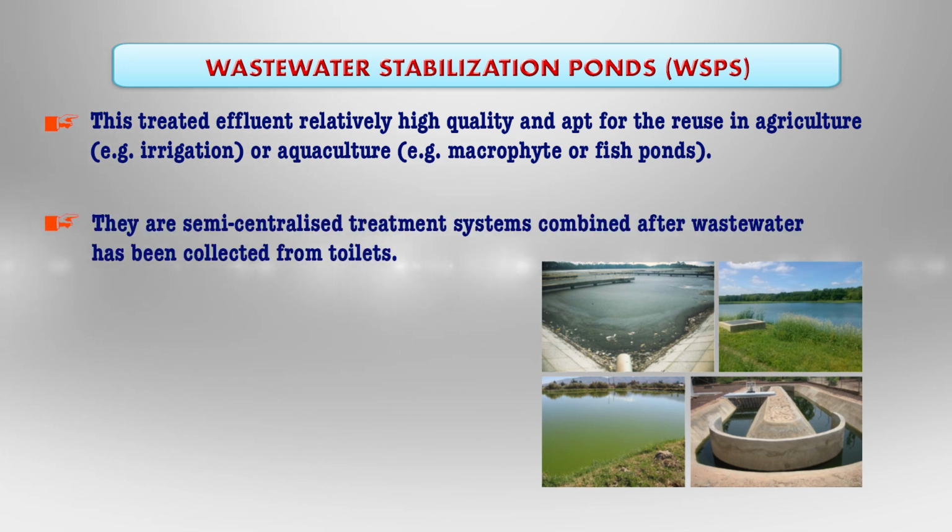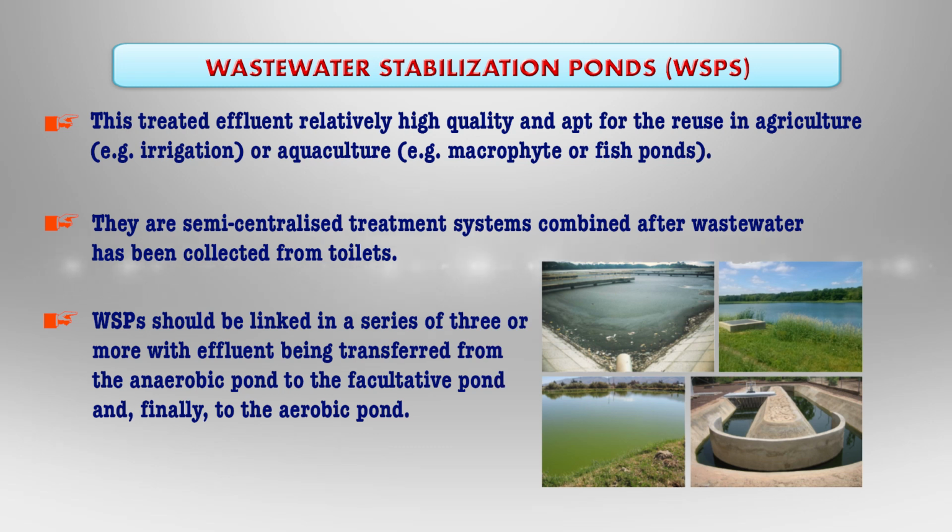They are semi-centralized treatment systems which can be combined after wastewater has been collected from the toilets. For the most effective treatment, these ponds should be linked in a series of three or more, with effluent transferred from the anaerobic pond to the facultative pond and finally to the aerobic pond.